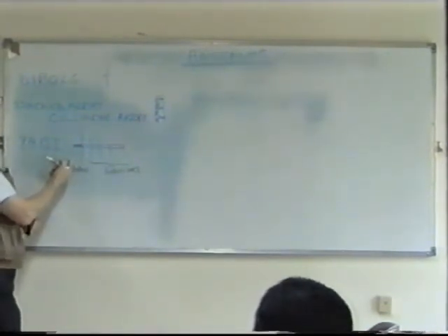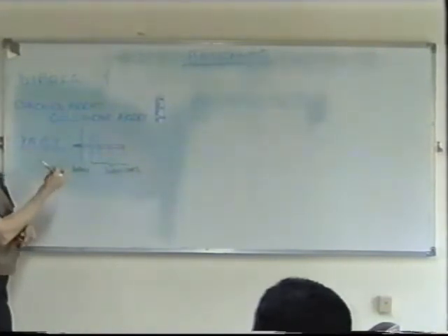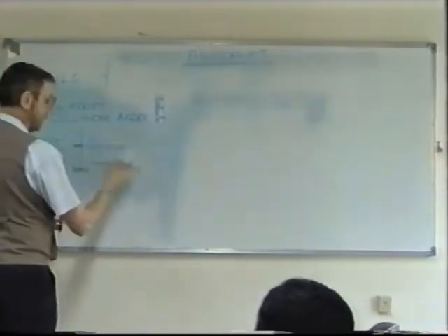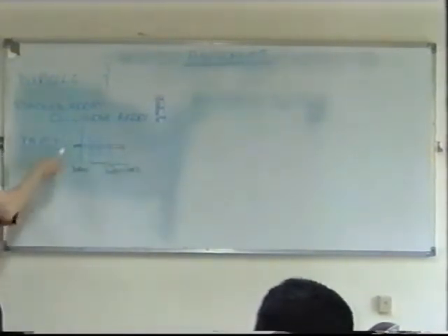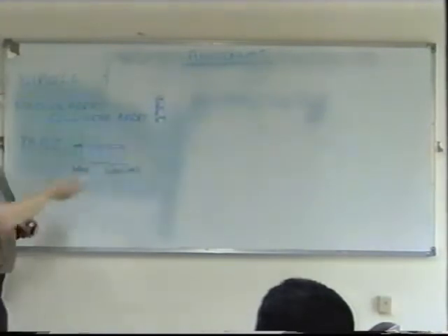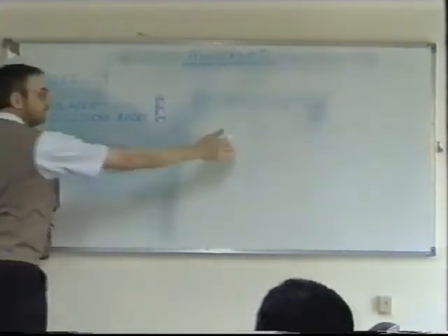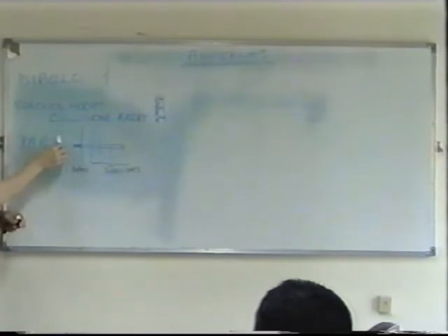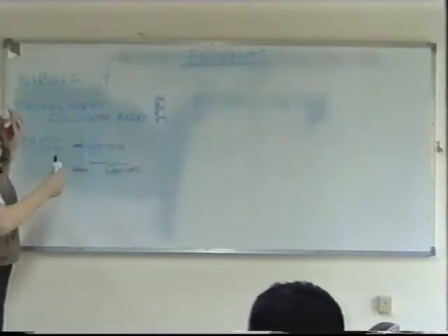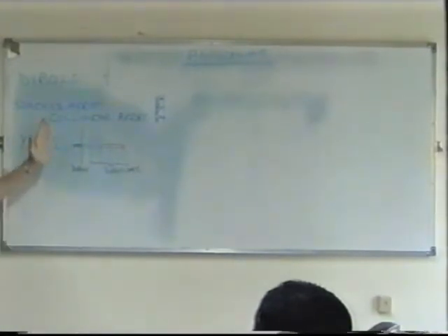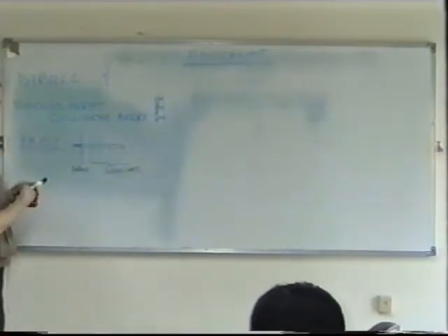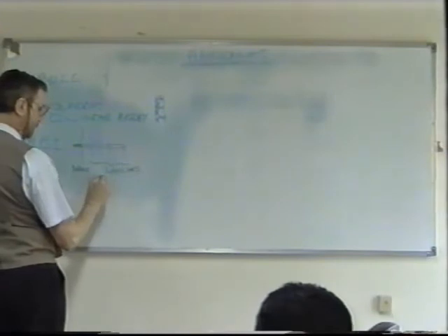What is the function of a reflector? Well, basically the same function as the directors. We want the wave to travel in one direction. So these direct the wave that way, but if I put an element at the back, depending on the distance of the element, that will actually reflect in the same direction. That's the reason. The whole idea is to increase the gain of the antenna. These are passive elements.